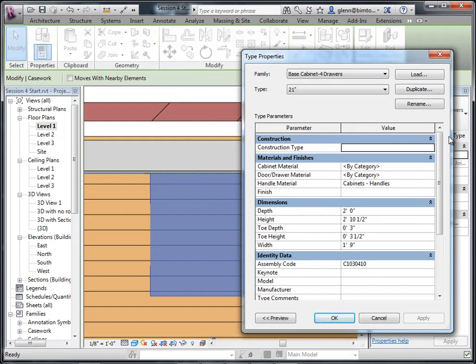And that'll take up that last 1.5 inches. So when you see these things at 2'10.5", don't worry about it. That's just really what's going on. It's always 2'10.5". Okay. For bathroom cabinets, the finished height is 32 inches typically. Okay, so we'll be 2'6.5" is the top of those.